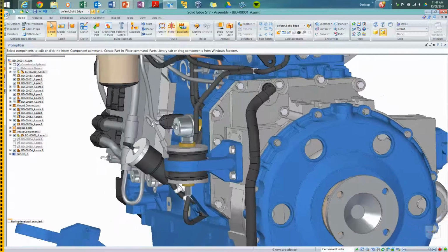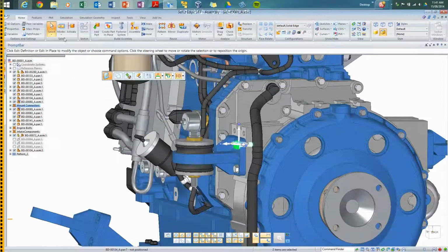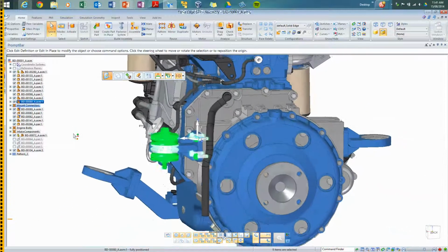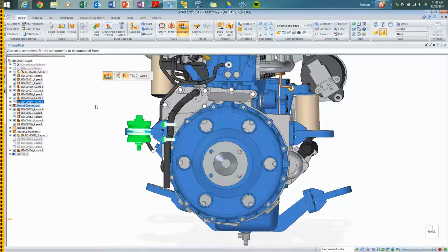So we'll run that in a second. What we'll do first up perhaps is just grab these components, select identical parts because I want all of those fasteners, and I'd also like that sub-assembly. Now I need a copy of all those components to go where the other three instances of that very first sub-assembly that we placed have gone, and duplicate components is going to help us with that. Because I've already got some components selected, Solid Edge skips step one. The select component step has been skipped because I've got parts selected already. If you haven't, then you just select them once you kick the tool off.